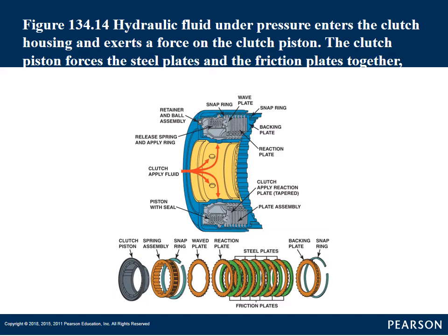They have a clutch pack in there called the 3-4 clutch pack. It's applied in 3rd gear and 4th gear. Those were a notoriously weak part of that transmission in the early days, and they would burn up pretty easily. So companies came out with kits. A lot of times they would hold 5 or 6 fiber clutches. A lot of companies came out with kits where you could put 8 or 9 fiber clutches in there. That increased the holding capability of that clutch pack.